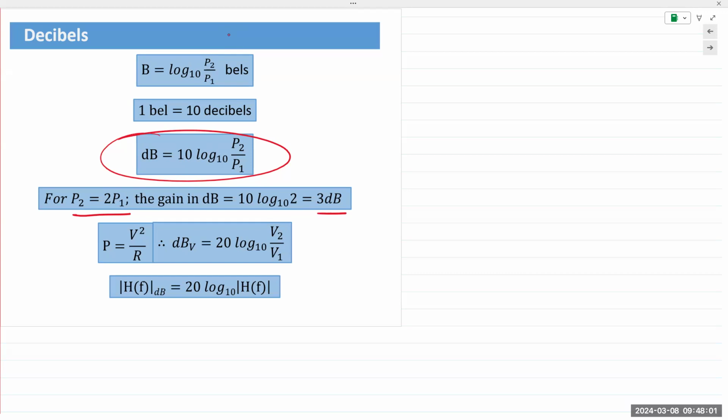And that is actually the amount that a human ear needs to increase or decrease to actually discern a difference in the levels. So if you have a 50-watt amplifier that's supplying 50 watts to a speaker, for us humans to be able to discern any change in the level, that minimum level is 3 dB, the power needs to double. It needs to go from 50 watts to 100. Okay, so the linear wattage does not mean much for audio engineers.